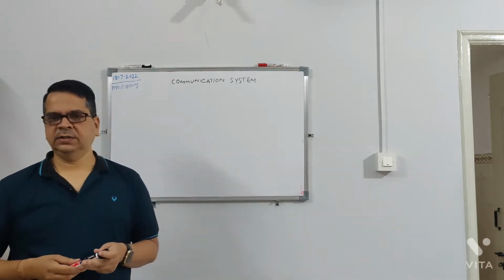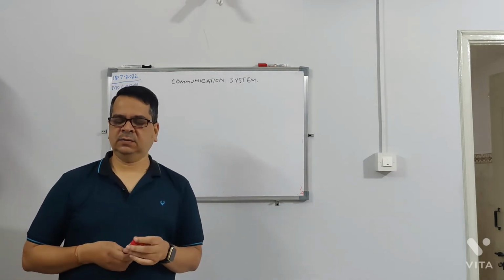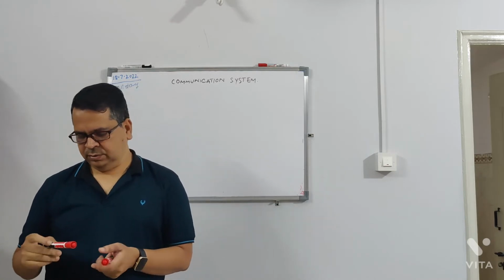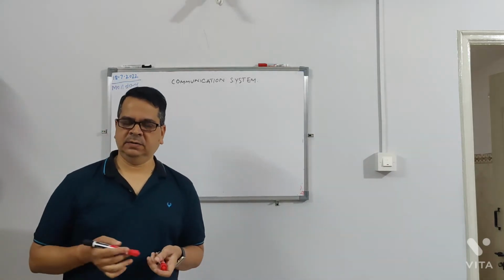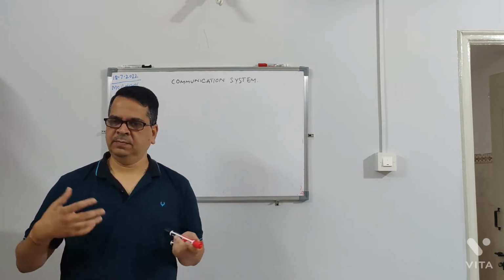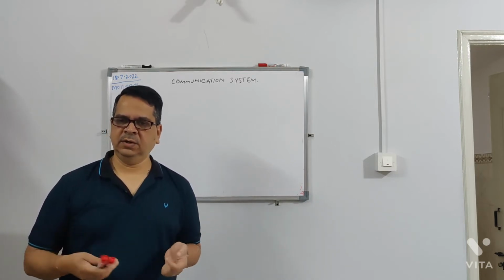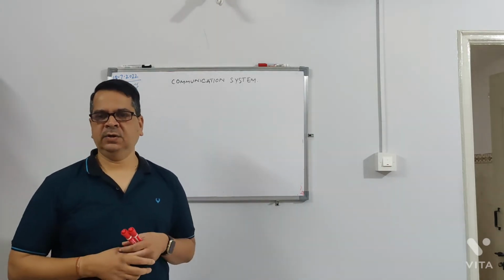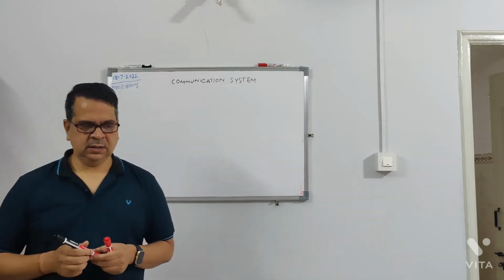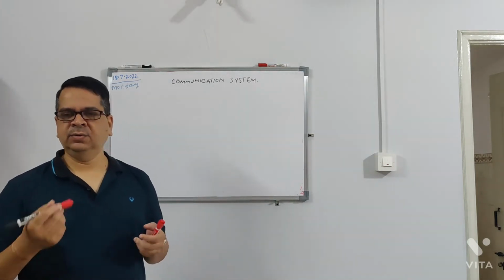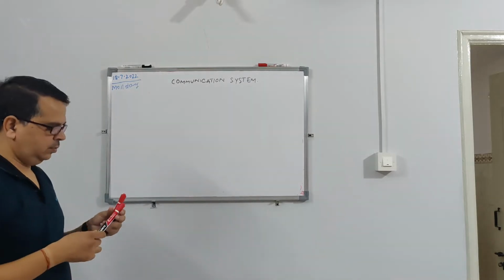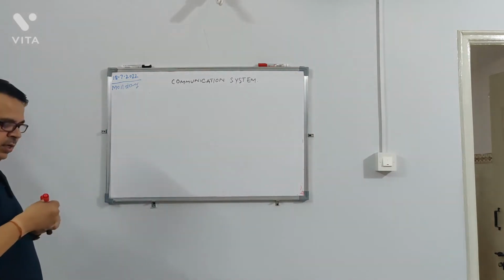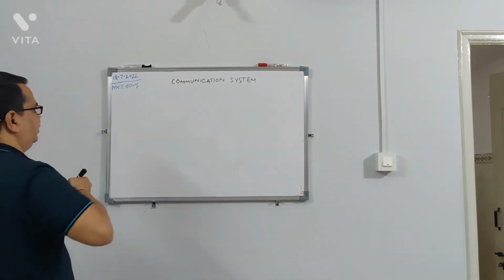Then we were discussing why do we need to do modulation? We were giving an analogy of a stone and a paper. If the paper is the base signal or the modulating wave, it cannot travel on its own. If you wrap it around a stone, which is the carrier wave, it can travel long distance. And another need of modulation is, if you don't modulate, the size of the antenna has to be very high. Okay, so that I will explain with a numerical.